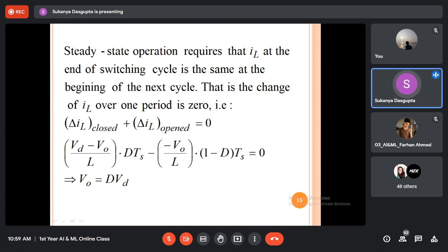That means by using buck converter or step down chopper circuit, the fixed input DC voltage can be converted to variable DC output voltage, in which the average DC output voltage will be just equal to 80% of input voltage, that is 80 volt.